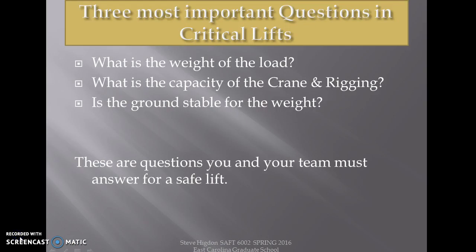In closing, the three most important questions in critical lifts that you should remember are: what is the weight of the load? What is the capacity of both the crane and the rigging? And is the ground stable for the weight that you intend to pick? These are questions that you and your team must answer for a safe lift. And it's not a one-person operation. Any critical lift is a team effort and will take the expertise of many people.